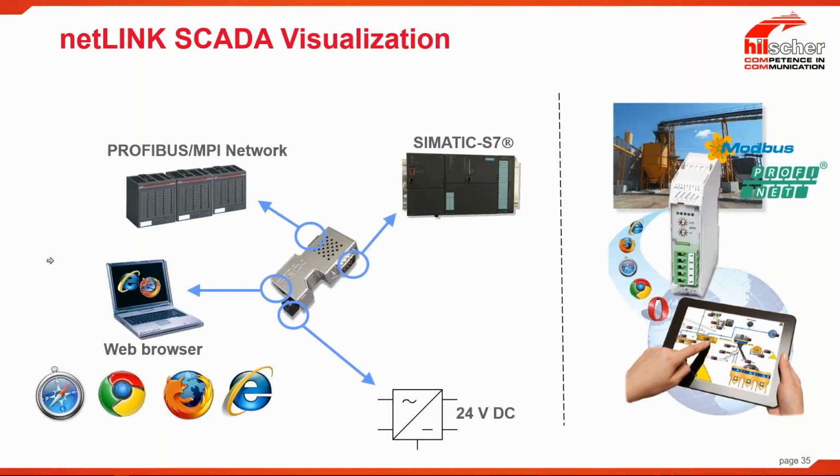Lastly, that same hardware can also be used as a web server, and that web server will basically give you visibility to that older Siemens controller. So again, you've got an older Siemens controller, not a whole lot of stuff available for it, but you can now add visualization for $1,000, and that connector will literally become a web server for you. That connector with our software will come together and become a SCADA system for you.